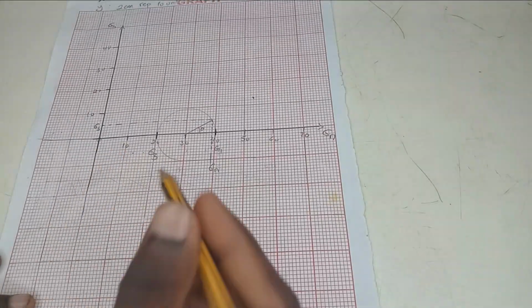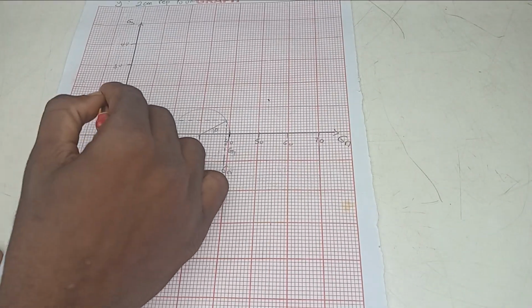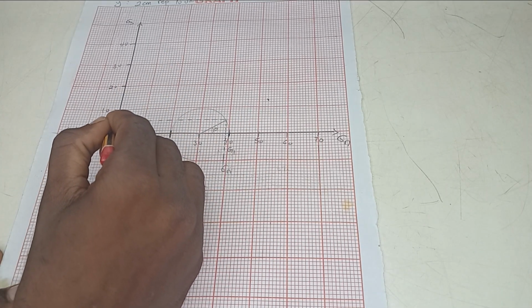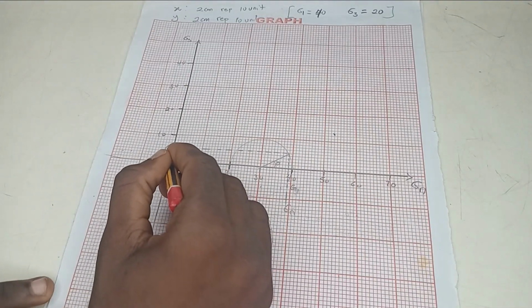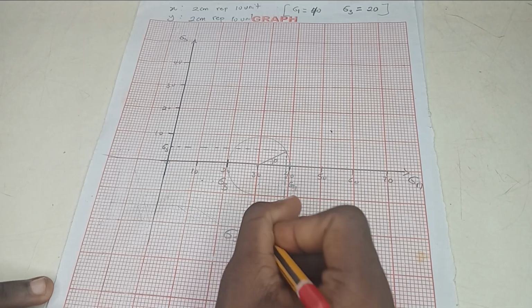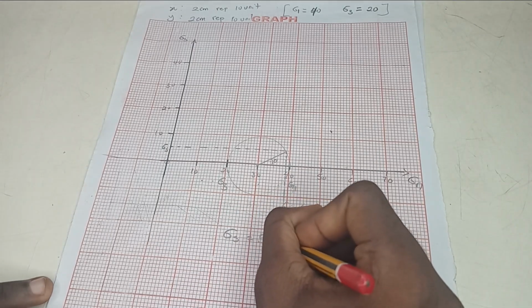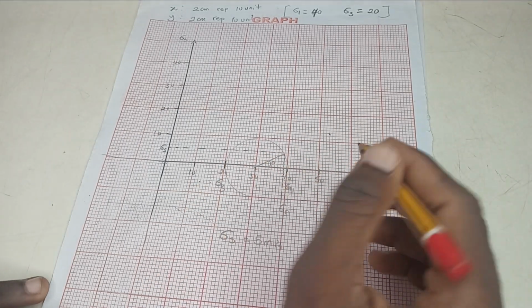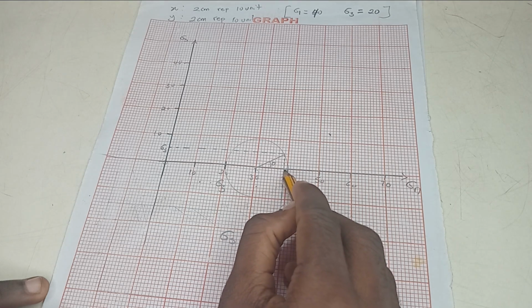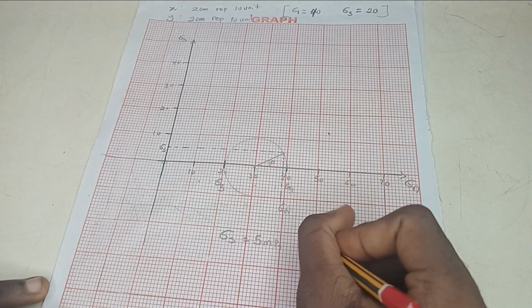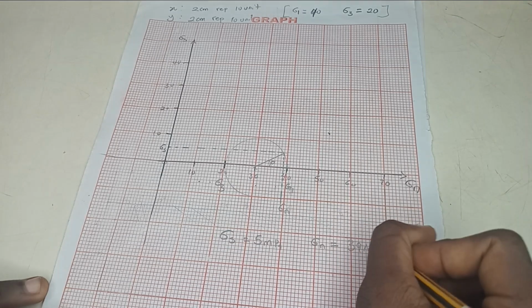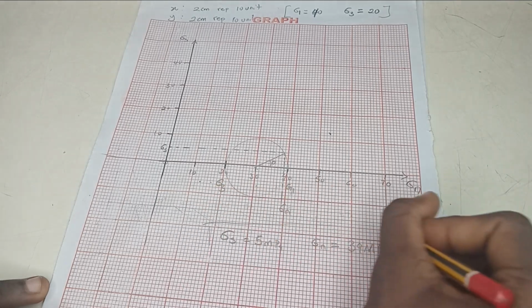We can get it. So for sigma s, we know that from here to here is 10 units, right? So each is moving by 1. This is 0, 1, 2, 3, 4, 5. So you can say our shear stress is 5. While our normal stress, this is 30, right? This is 31. You know that to this place, that is 39. So our sigma n is 39. If you use the formula you will still get this.